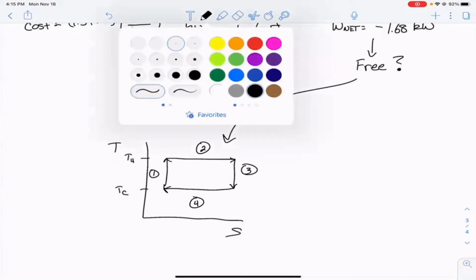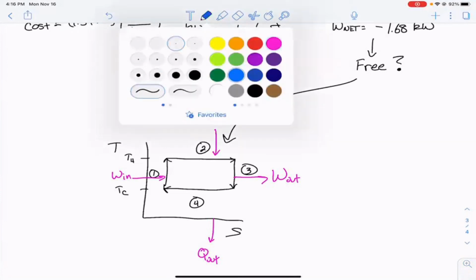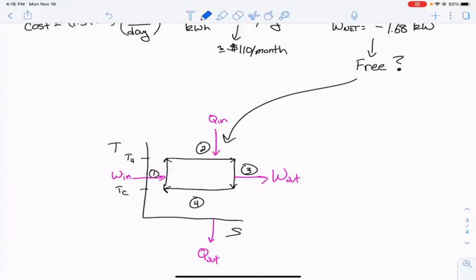And we like to label it very simply as Q in, Q out, W out, and W in. But that, quite frankly, is a little bit oversimplified because steps 2 and 4 are isothermal. And if you think about this as a closed system, as an approximation, for step 2, that would mean that delta U is equal to Q in plus just something that we'll call W prime.